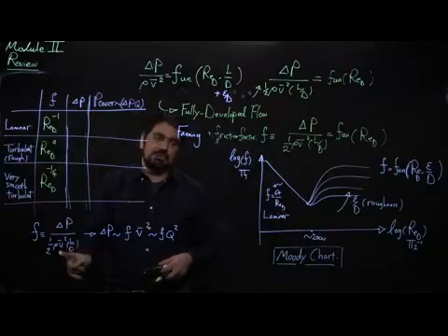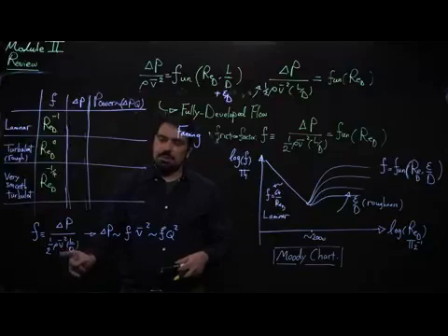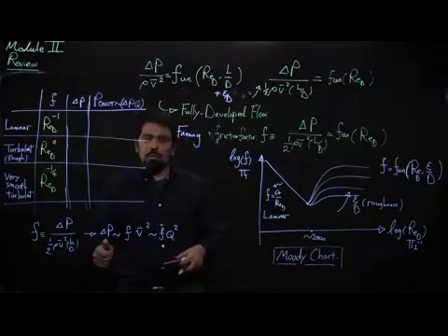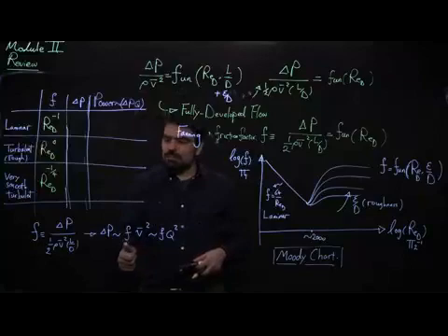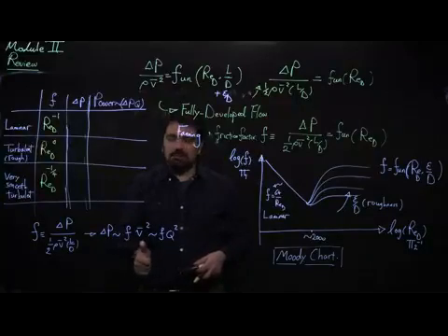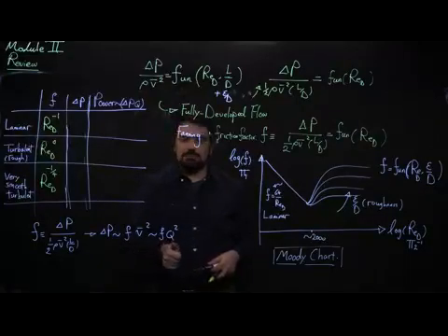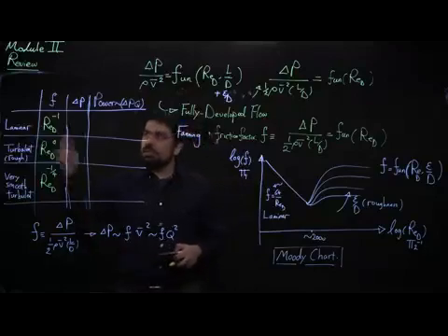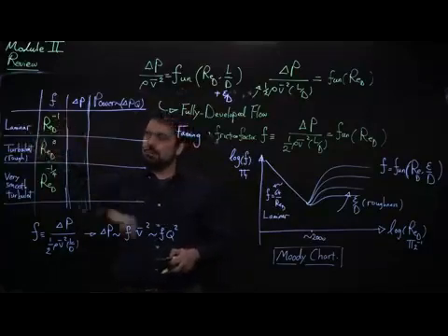So as you increase the volumetric flow rate, V, which is exactly linearly proportional to the volumetric flow rate (V is the volumetric flow rate divided by the cross-sectional area), is also increasing. So your overall pressure drop will be that friction factor relationship multiplied by V squared, which is F times Q squared.